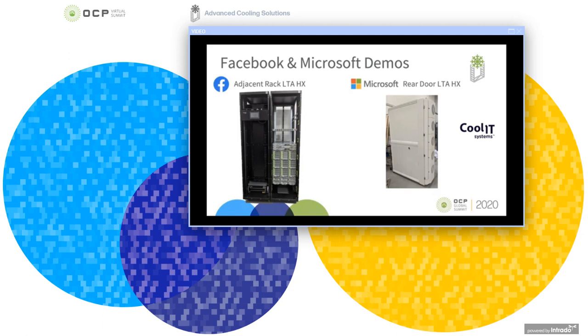The bottom 4U are occupied by the RPU. There are 10 efficient 200 millimeter fans with N+2 redundancy, and the target approach temperature of this heat exchanger at 35 kilowatt heat load is 10 degrees Celsius. Now, the 35 kilowatts can come in the form of either one high density rack as shown in the photo, or 2 lower density racks, both connected to the RPU in parallel.